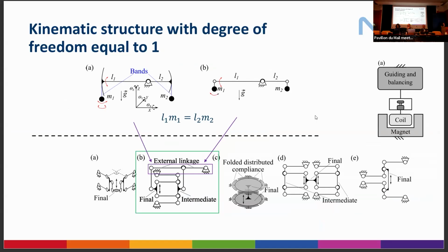In A, when you use a pulley, you mainly move along a perfect trajectory when things are well aligned. With a beam, you have some cosine, so you have an arc of motion when you move the beam. Now, if you want to make a 1 degree of freedom motion, you want to attach to those mechanisms some guiding to make sure it's moving along a perfect trajectory.